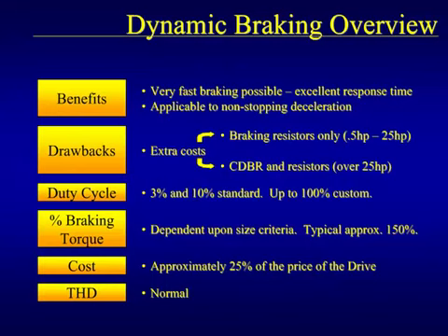On the smaller units, only resistors are required. However, on larger units, both the resistors and braking transistor units are required. This additional cost can be up to 25% of the drive price.